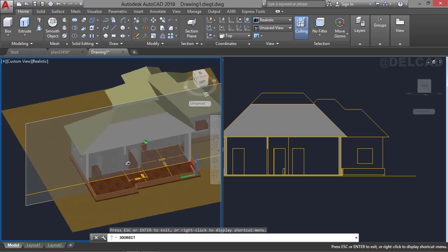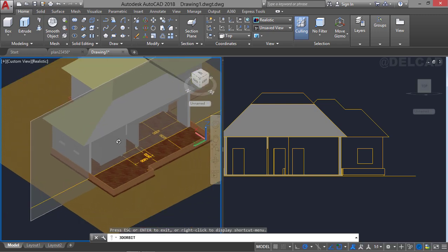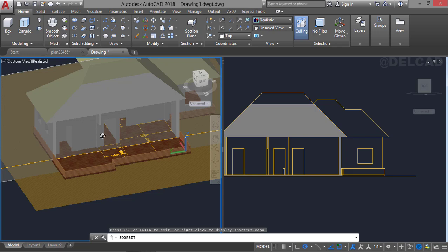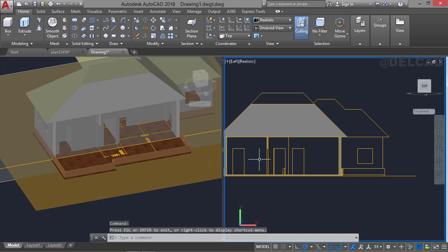And as we keep moving across, if you take a look at this also, we have this very particular portion of the wall that is being cut at the top, and below here is an opening. So if you take a look at the section, we have the top part of this being shaded, and then below here is just an opening also which is not shaded, showing that there is an opening at this very particular point. And then if we orbit again, after this portion we have the door, and that is represented here with just an opening with a yellow line, just like this.